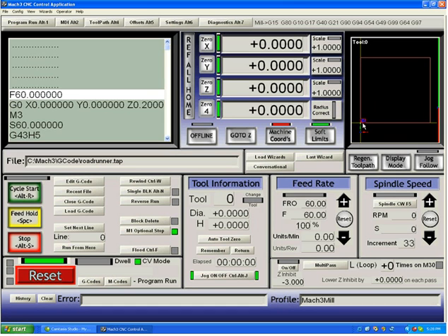Most people would not want to cut a job at that position, however. They would want to cut a job maybe by throwing the material into the center of their mill's table. Because of that, we need another coordinate system. The machine coordinate system is not going to do it. The machine coordinate system simply cares about 2 things. Where is the home switch? Here in this position in the bottom left-hand corner. And what is the size of your table?